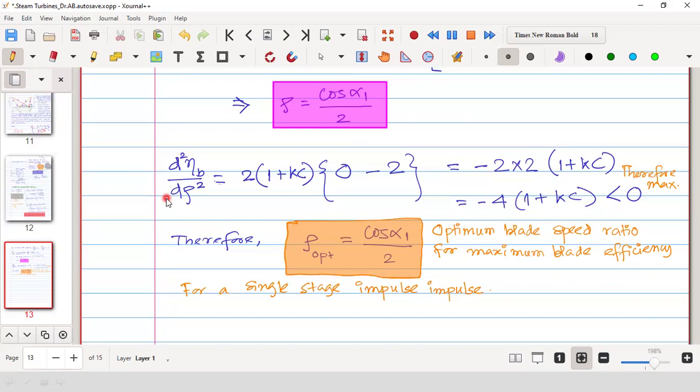One thing. Another thing is that if the turbine rotates at that high speed, then due to the centrifugal action, the blade and the rotor will have high vibration, maybe with a slight imbalance of the rotor. There will be high vibration, and also high centrifugal force on the blades, and the blades may break.